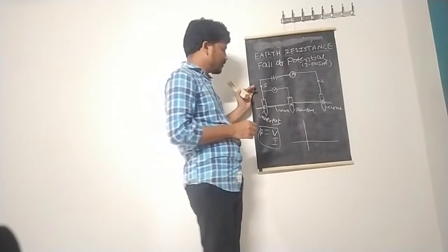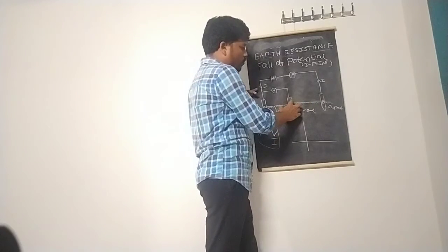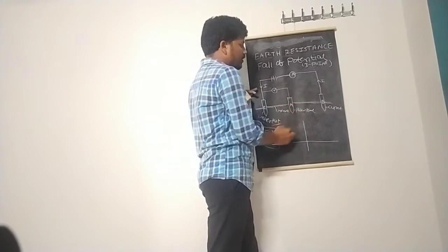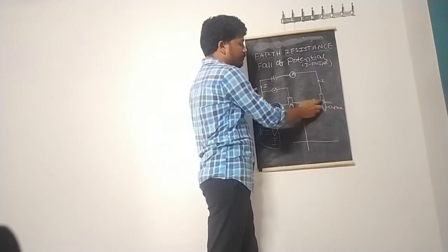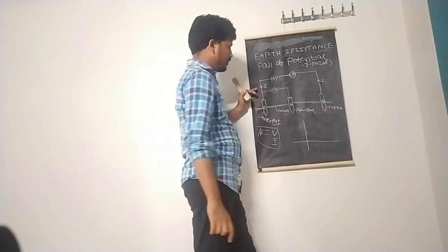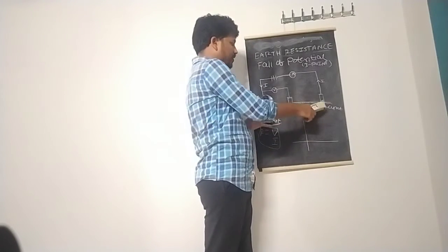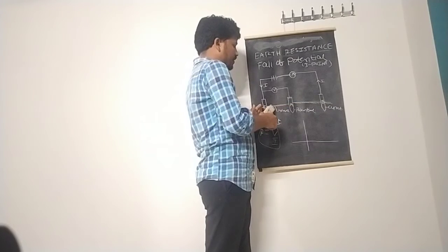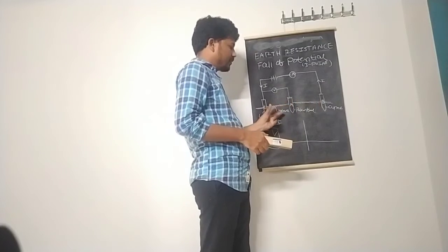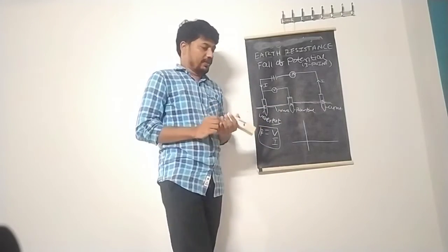Here one thing we have to see is that there are two electrodes, A and B. A is the mobile electrode, which can move either this side towards capital E or towards B. B is a fixed electrode, and E is already fixed. This is the soil. Generally, to avoid layer interference, you maintain equal gaps from E to A and A to B. For example, if the gap is 15 meters, the total is 30 meters. If it is 20, the total distance is 40 meters. This is generally to avoid interference.